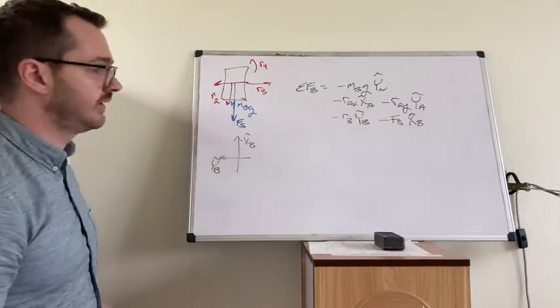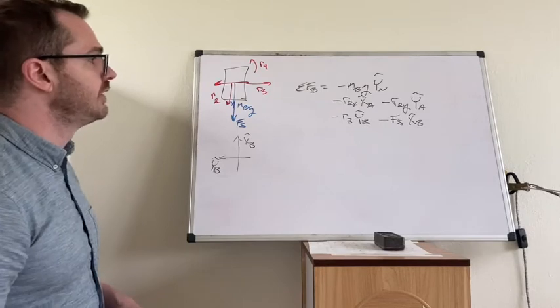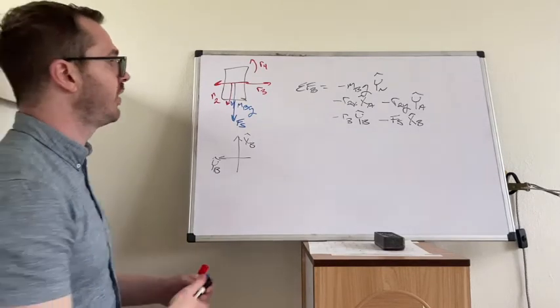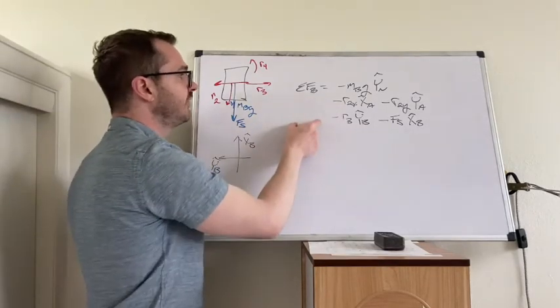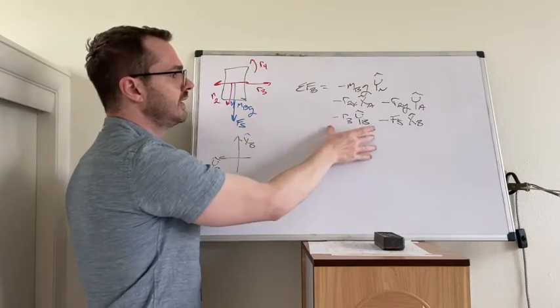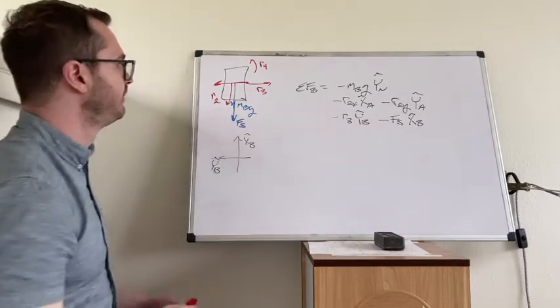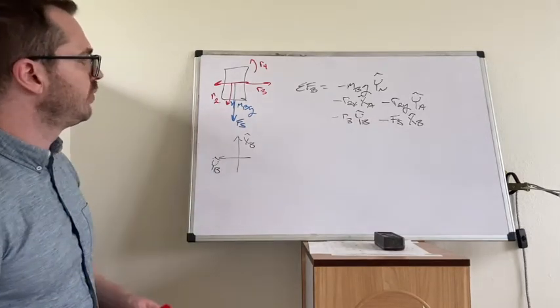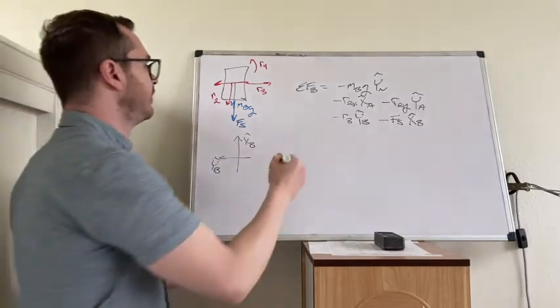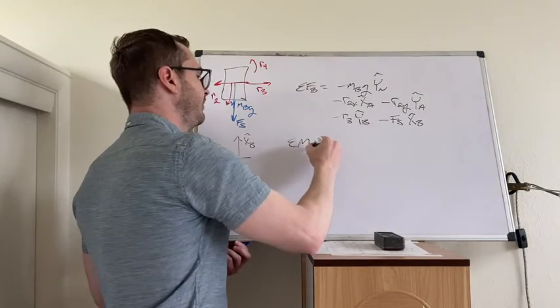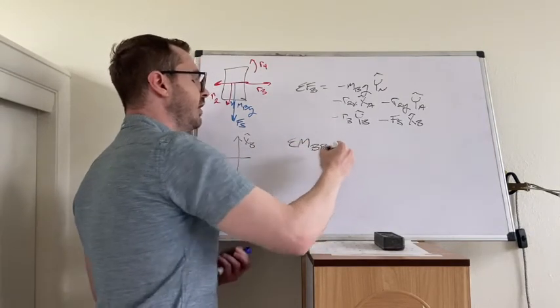Again, this is acceptable. If we wanted to numerically sum all these up, and I wanted to know the value of the sum of forces in each of the three directions, clearly we would need to put all of these in the same frame and then add them up. Next, we want to do sum of moments on this. We want the sum of moments on B about B.